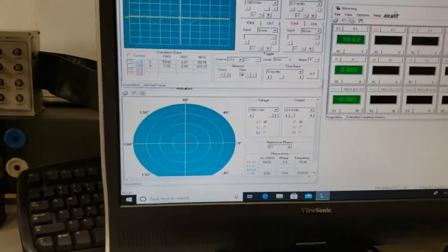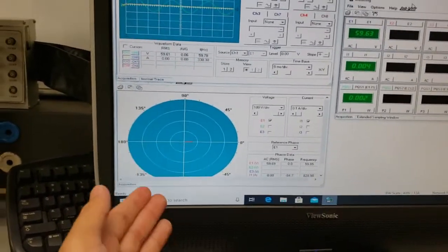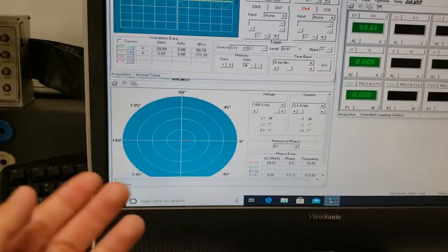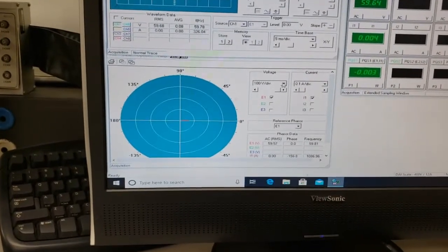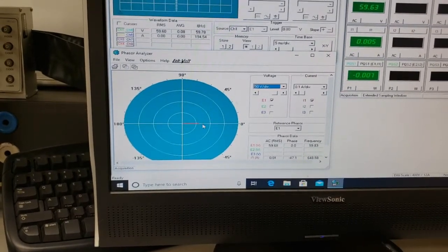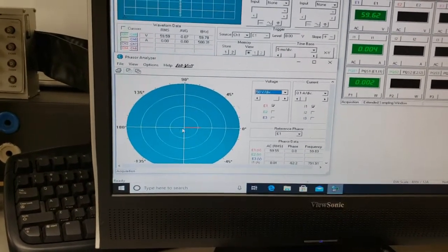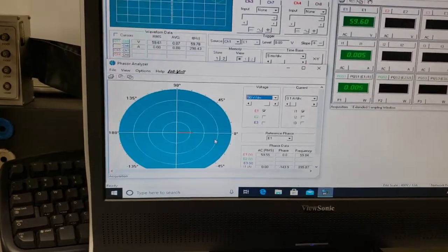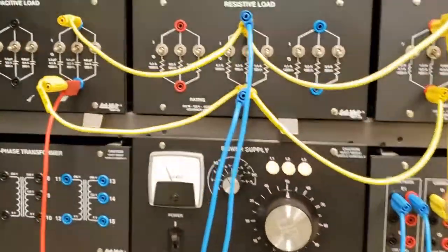And then this is the phasor window, and this will allow us to see the phase difference between voltage and current, and that's what it's most useful for. Actually, I'm going to adjust the voltage phasor so it's 50 volts per division, so you can see it a little more there. But anyways, once the current waveform comes up, you'll see a pink one on top.